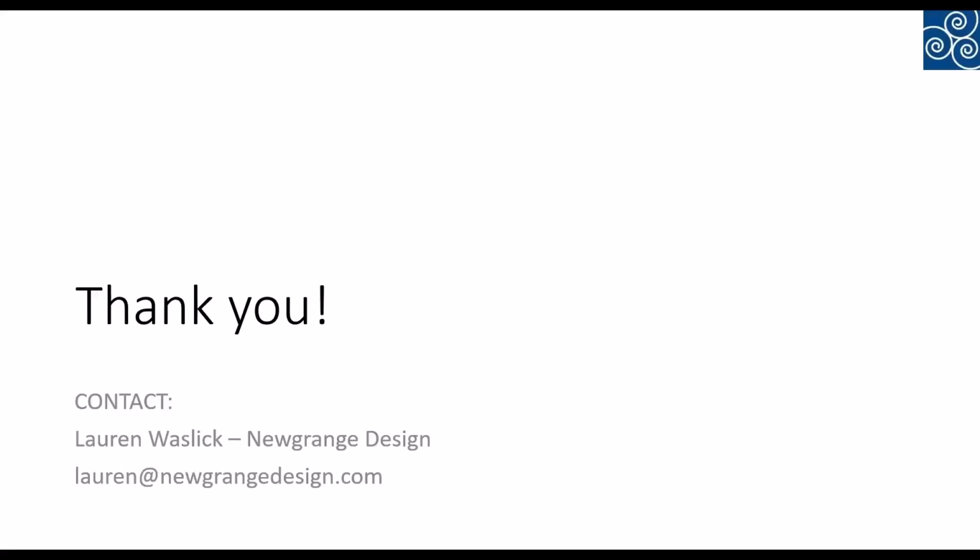I don't know any rules of thumb off the top of my head for this, but it is something to be aware of. How many times is this going to be installed and uninstalled, and does that impact the types of materials you might choose? Your fab house might be able to guide you towards more reliable or robust materials in choosing the flex that would still work with your bend radius or the different coverlays, things like that. In the next webinar, I'll also talk about things like epoxy bead that will help save your rigid flex transition and prevent it from tearing.